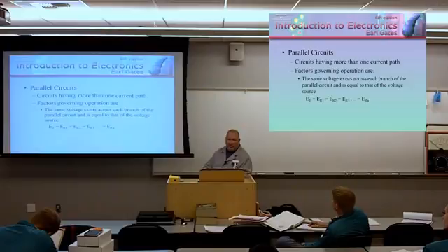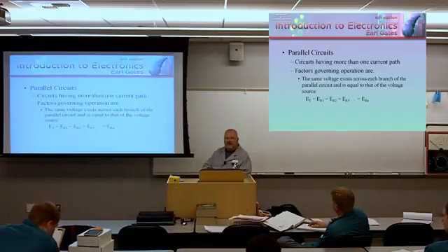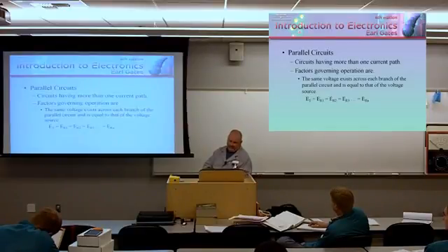If you know something's connected in parallel, you could assume I should have the same voltage across that. Well, sheesh, the thing's still not working, or it's working kind of goofy. It's hard to get to. Well, sometimes you have to remove that access panel, go in there and take the reading. Holy cow. Everything else in parallel is at 12 volts. This is only at 9 volts. I'm missing 3 volts. You find the missing 3 volts, you found the problem. It's that simple. One of the most powerful tools.